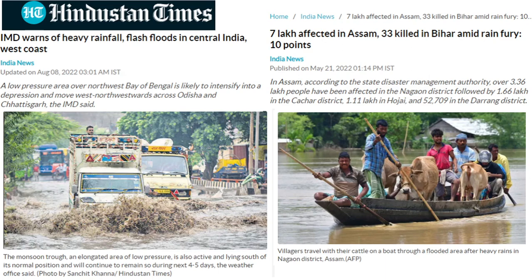The main cause of this flood in Patna was the choking of the drainage system. Sometimes choking of the drainage system causes an artificial flood, but the main reason for floods is the high amount of rainfall in the catchment area, as well as ineffective drainage of rainwater.